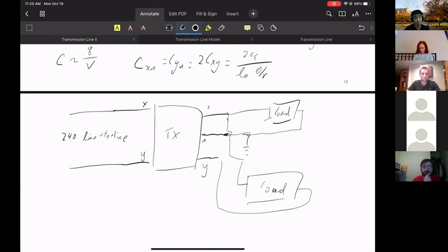Okay. So this is sort of the breaker circuit you have in your home. So pretty much, when you start using the X to Y connection, you're getting 240, and so you can pretty much do double the current then, right? Yeah, no, you want to reduce current. The higher voltage is to reduce current. You get more power with half the current. Your box in your home is rated by current. So what if your kitchen appliance or your washer and dryer needs more power? The way you do it is you go up on voltage to stay under your current limit. Okay, that makes a lot more sense. Thank you.